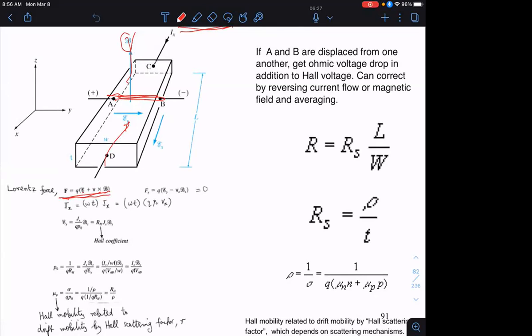What was the problem number? 3.17. The first part asks to calculate the hole concentration, and we're given the electron concentration and NC and NV. So are we supposed to express that in terms of a temperature dependence? Because you can calculate Ni using just NC, NV, and the electron gap. Whenever I don't specify temperature, you can assume it's room temperature, which is 300 Kelvin.